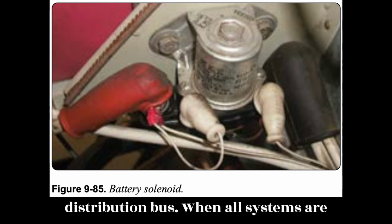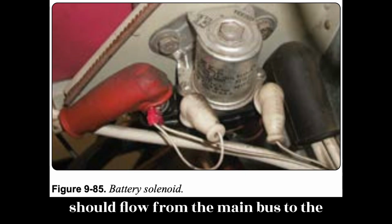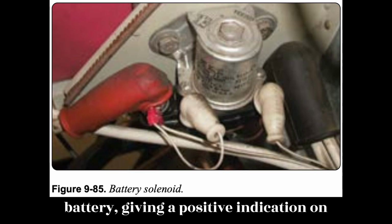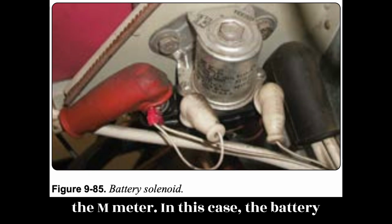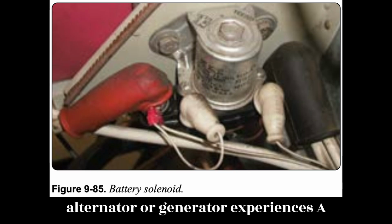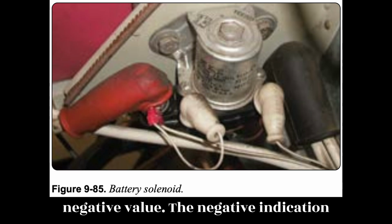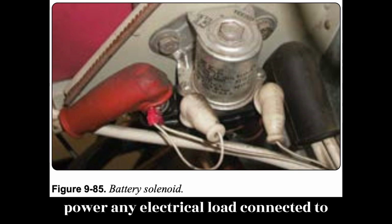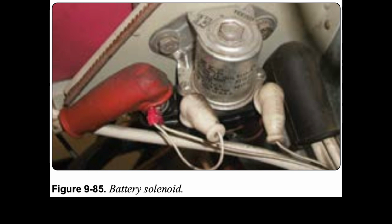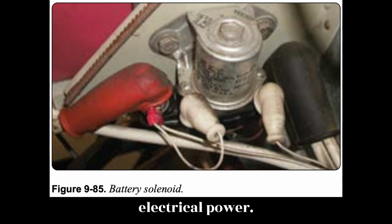to the distribution bus. When all systems are operating properly, battery current should flow from the main bus to the battery, giving a positive indication on the ammeter. In this case, the battery is being charged. If the aircraft alternator or generator experiences a malfunction, the ammeter indicates a negative value. A negative indication means current is leaving the battery to power any electrical load connected to the bus. The battery is being discharged and the aircraft is in danger of losing all electrical power.